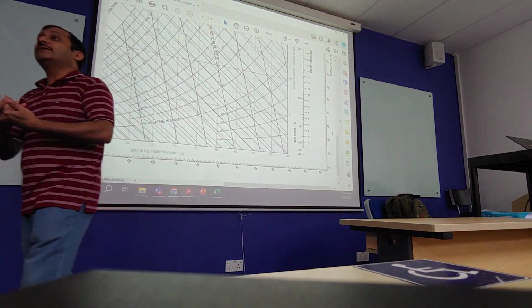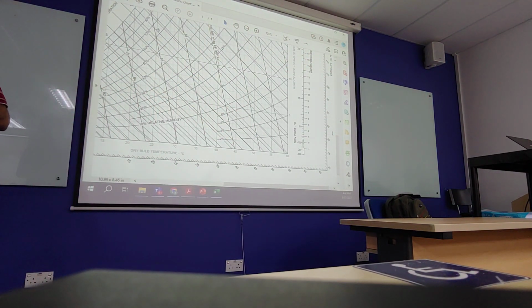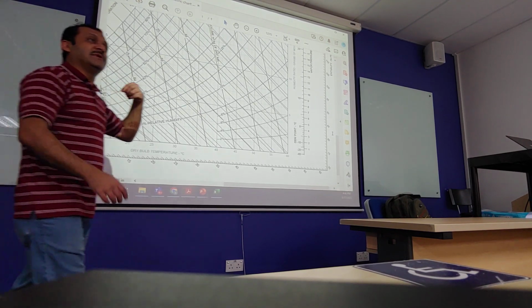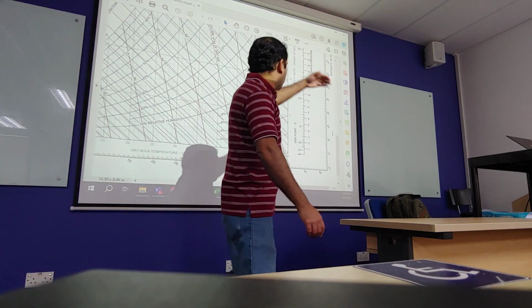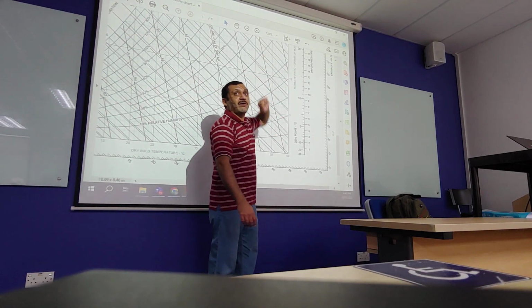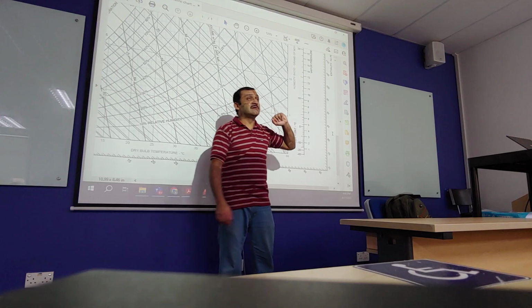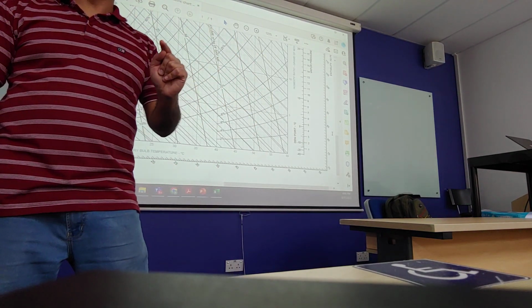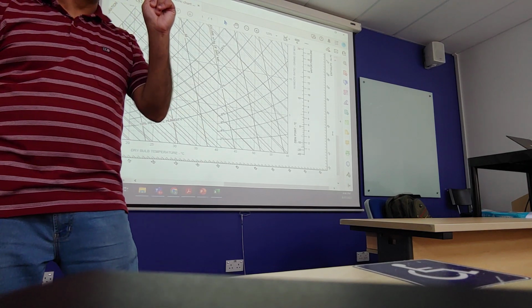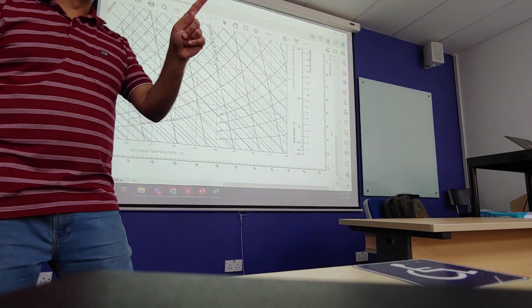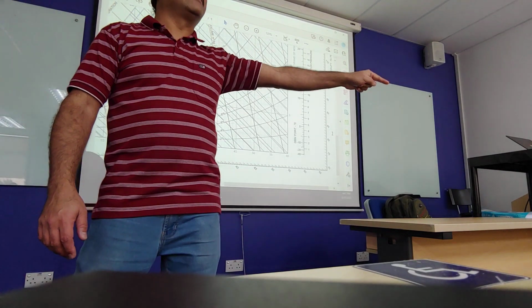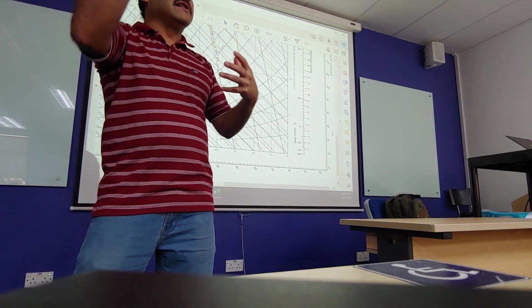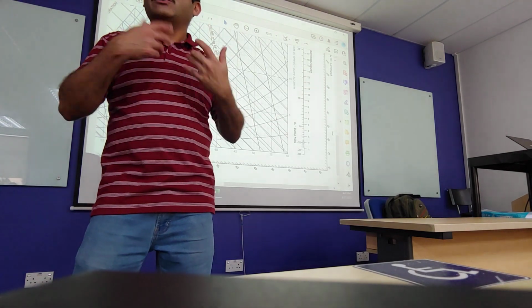And how do we diagnose that? By just identifying pressures, temperatures and humidity. So, for example, if we are expecting the moisture content to be reduced from, let's say, 20 grams to 10 grams, and your sensor is not detecting that, there are a couple of possibilities. First possibility is definitely the sensor might be faulty. But then if we are getting a complaint from the occupant saying it's getting too humid, too uncomfortable, then definitely the sensor is not faulty, because humans are also feeling that.